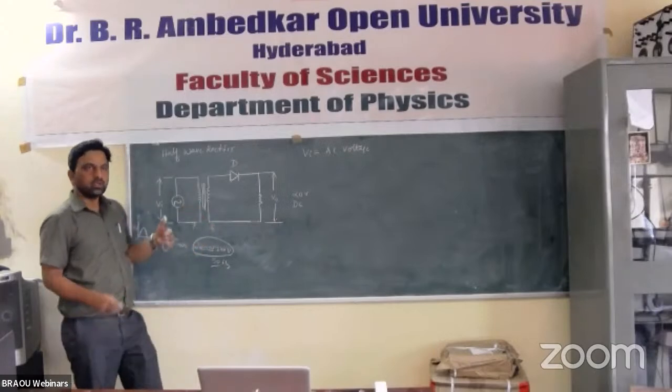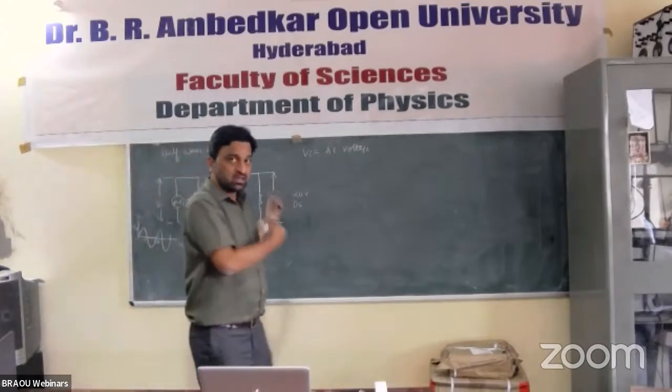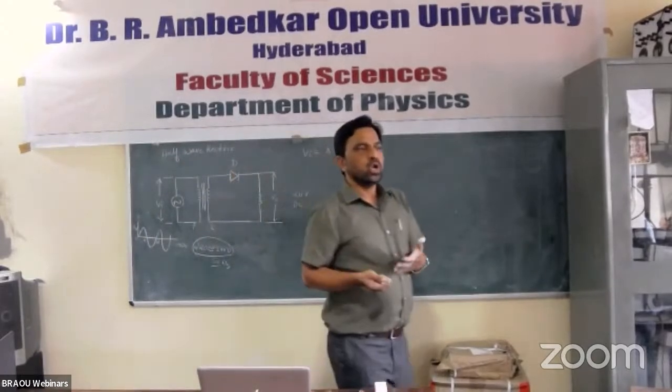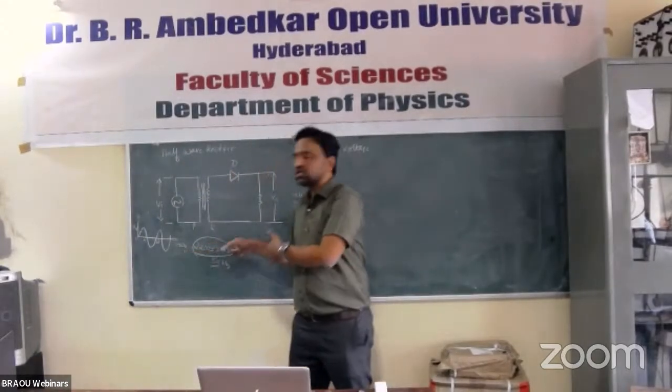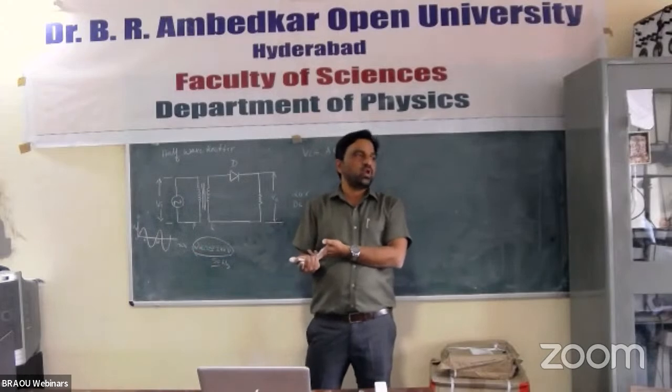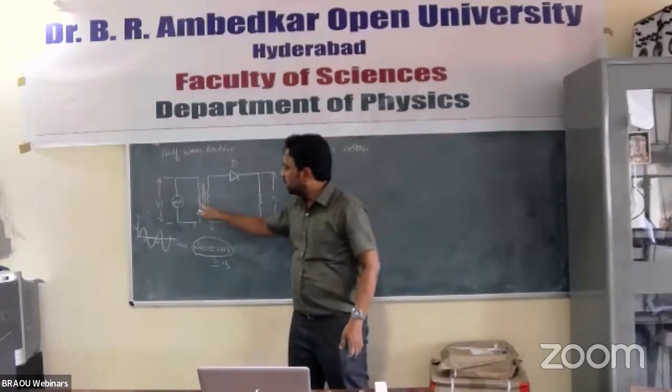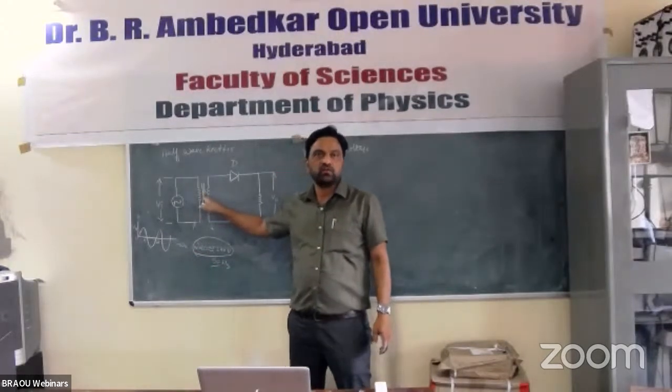Transformer. Suppose you require a DC voltage more than this. Say you are getting 220 volts, and suppose you require some 300 volts of DC voltage. Then we'll use a step up transformer here.